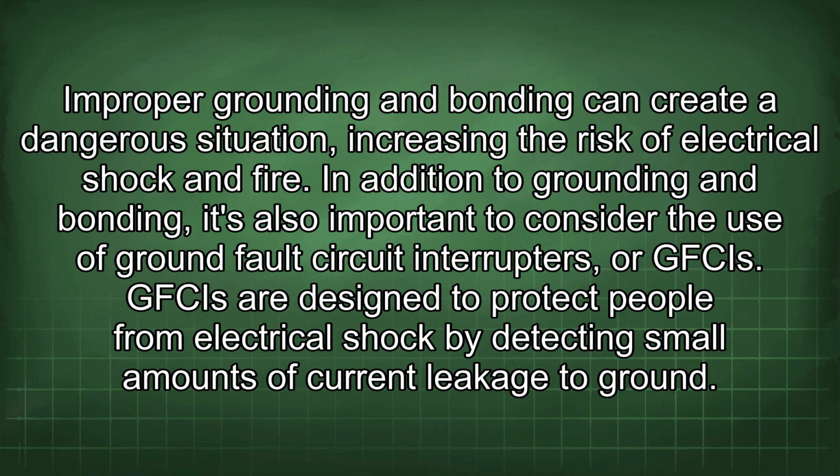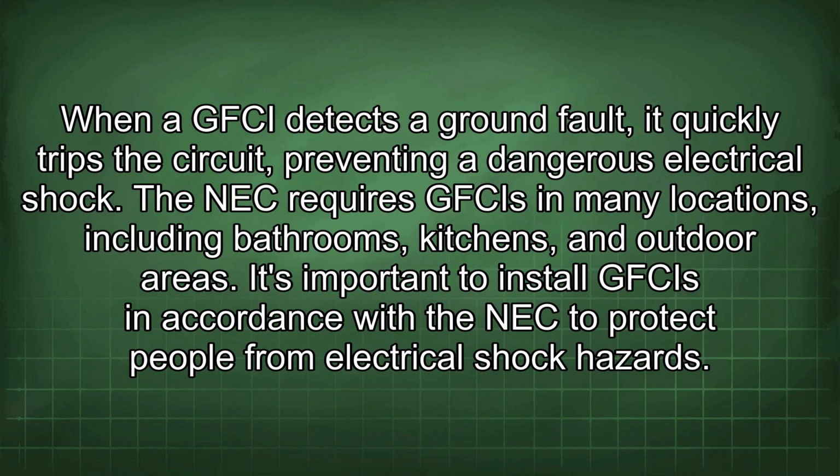GFCIs are designed to protect people from electrical shock by detecting small amounts of current leakage to ground. When a GFCI detects a ground fault, it quickly trips the circuit, preventing a dangerous electrical shock. The NEC requires GFCIs in many locations, including bathrooms, kitchens, and outdoor areas. It's important to install GFCIs in accordance with the NEC to protect people from electrical shock hazards.